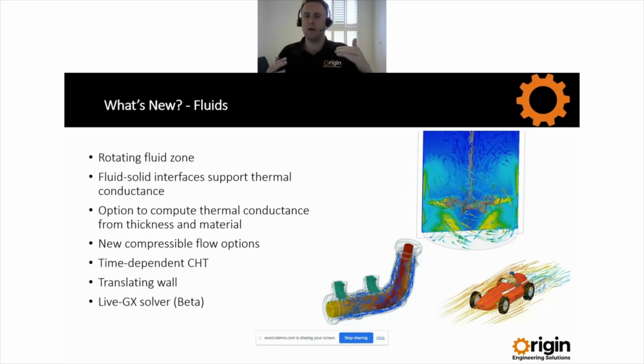So setting up global mesh settings, and local mesh settings for particular areas of the part, which is really useful for dealing with complex geometry. What they've now done is allow you to use the full mesh controls that you would get in refine mode, but actually use the GPU solver to solve the problem. That is going to enable us to deal with much more complex geometry, but solve it with the speed of the graphics card, which is great for getting really fast results.